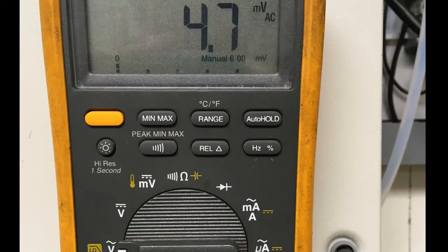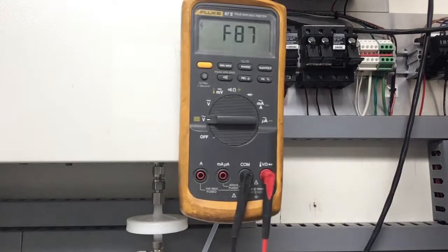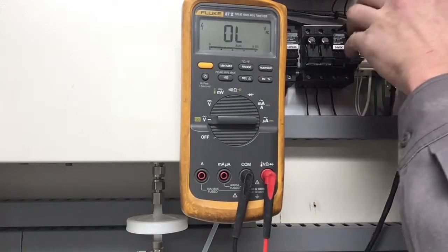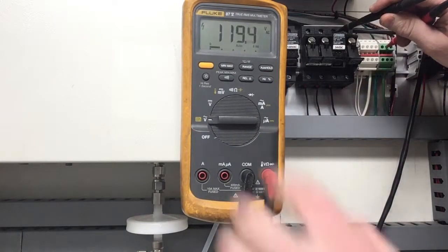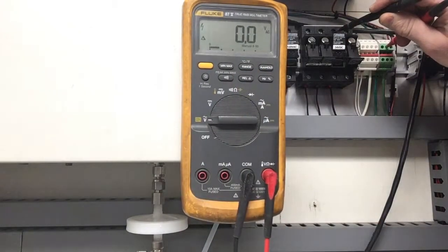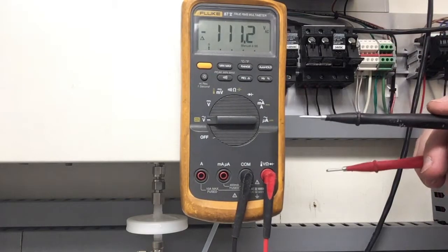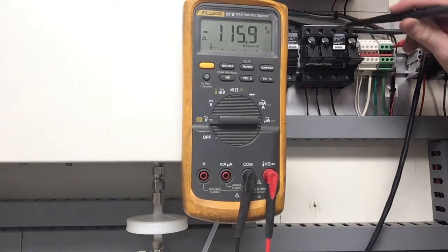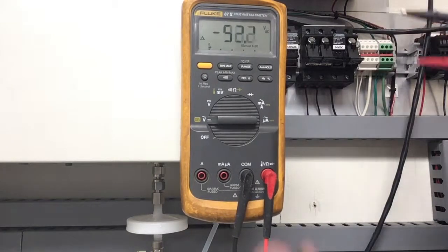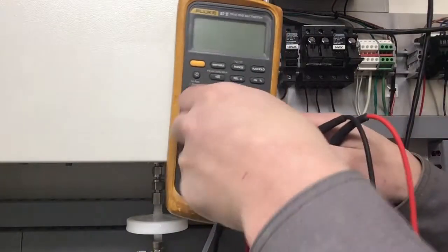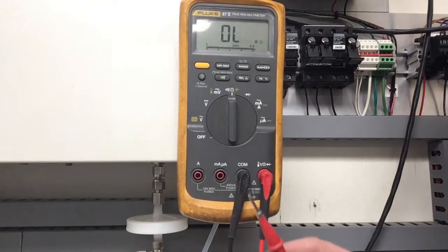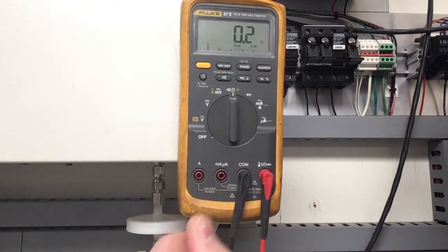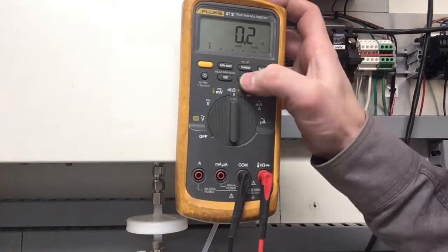The REL button places the meter in relative mode. When this mode is activated, the value that is present on the leads is used as the new zero condition. All measurements after the activation of this mode will be in reference to the value that was present at the time of activation. This can be used to get a better idea of oscillations to a base value, to compare multiple measurements to one common, or to negate the natural resistance of the meter and test leads.